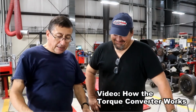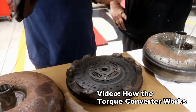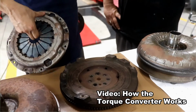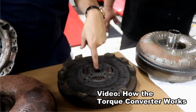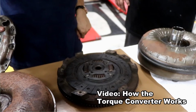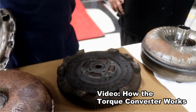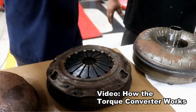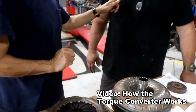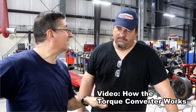It's a hydraulic clutch. Look, this is a mechanical clutch, Danny. You remember? The pressure plate, the friction plate, and the flywheel. The friction plate is moving free. Here enters the input shaft of the manual transmission. The input shaft of the manual transmission is always connected here, and it is free if the clutch pedal is applied. If the clutch pedal is applied, it's free, and the transmission is separated from the engine, and you can change the gear.